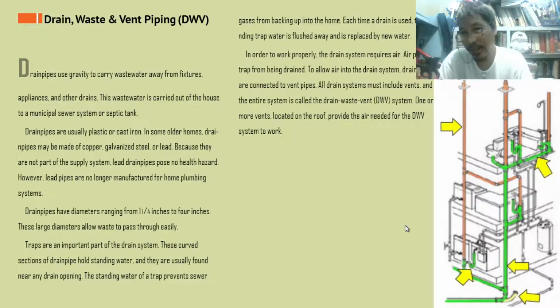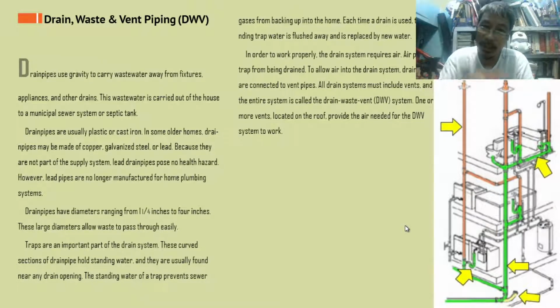That's why it's called a trap, because a small, desired amount of water is trapped, and that is important because it prevents bad smell from getting out of the pipe and going inside the habitable area of the occupants.